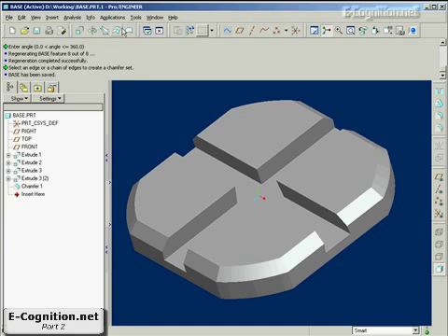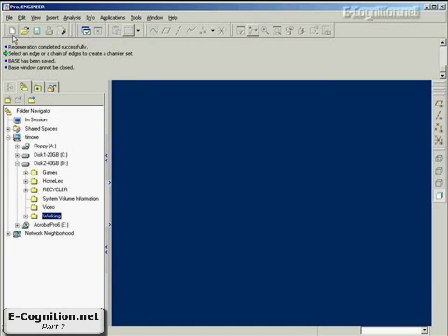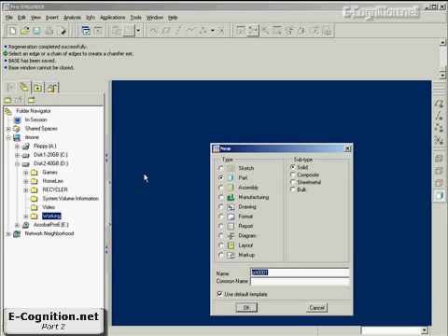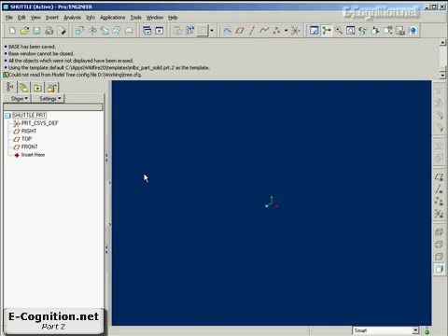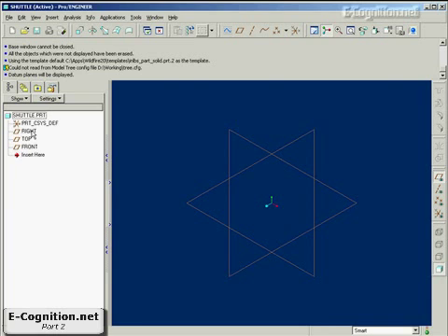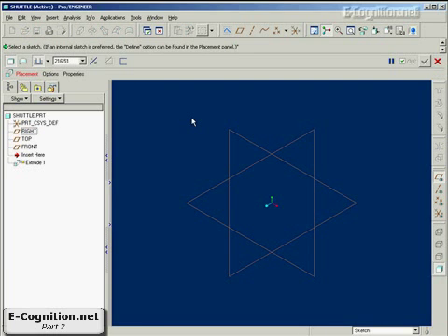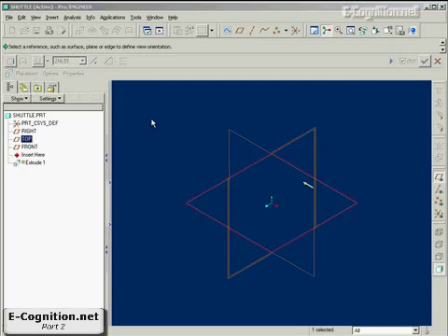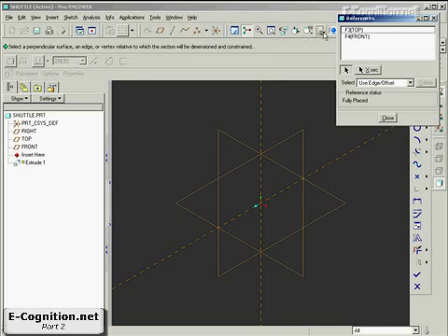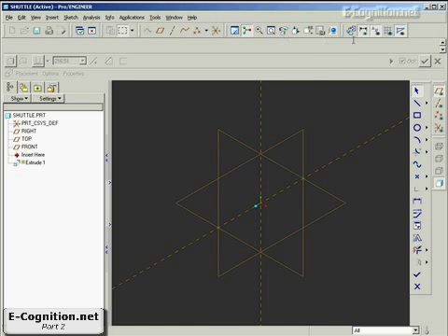Next we'll do, close this window, we'll make a new part, and we'll call this one Shuttle. Now the shuttle, turn on the datum planes, the shuttle is going to fit into those slots. So let's make a protrusion that goes on both sides of this plane that I selected. The references are fine. Go straight to the sketch view. Oh, here it is.